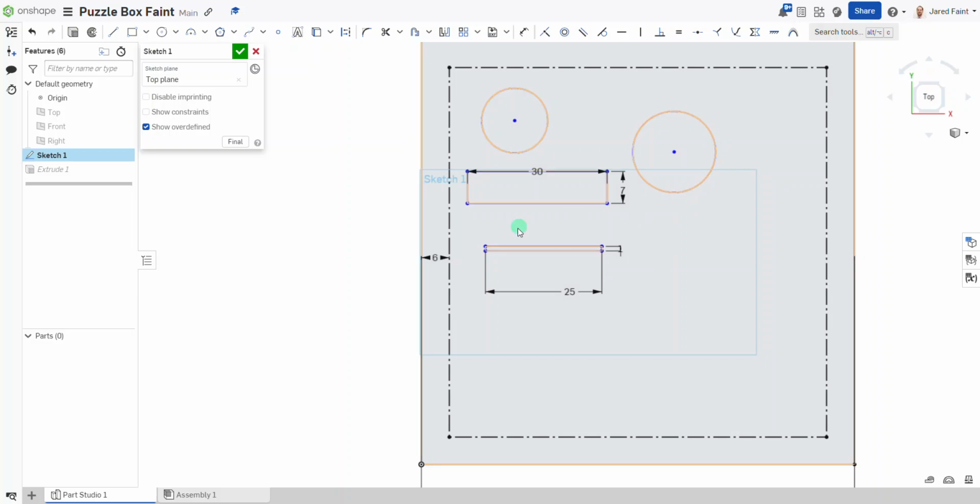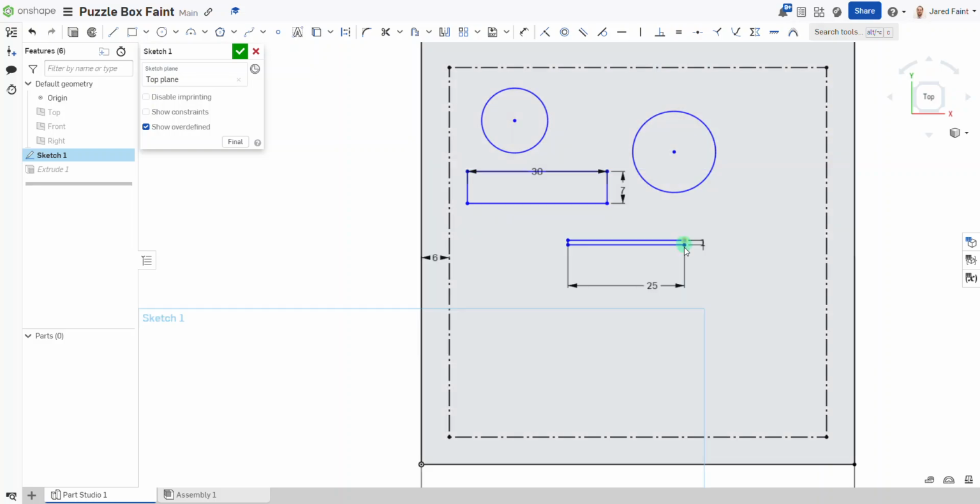So I could do something like that. Now, when it comes to designing your shape, at the moment, you can see I've got that rectangle set up, but he's locked in and he doesn't move around. You've got this aligned rectangle, so if I want to do something like that, I could actually then do it on an angle as well. So you've got a few options on how you design that one. So if I want to make those on a specific angle, I can go back to my dimension, and I might go, all right, well, I want that to be from that angle and be on a 35-degree angle. So I can sort of start constraining a little bit of these lines as I go as well.